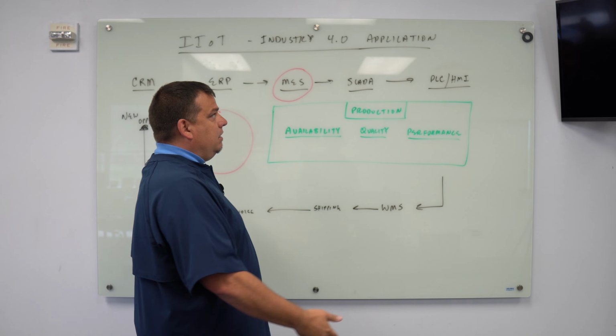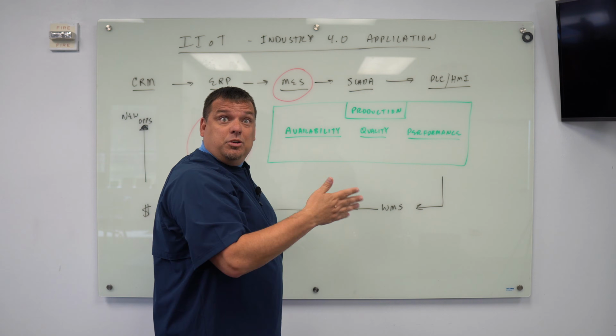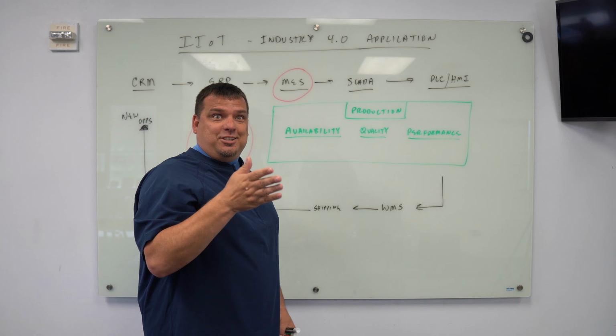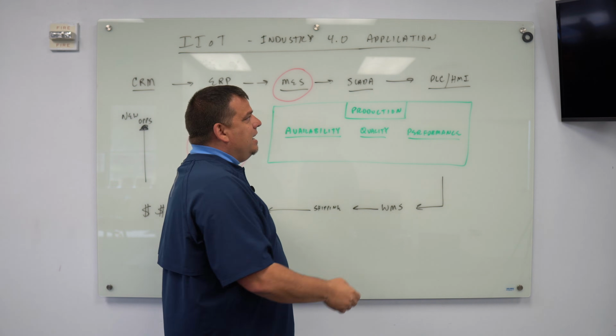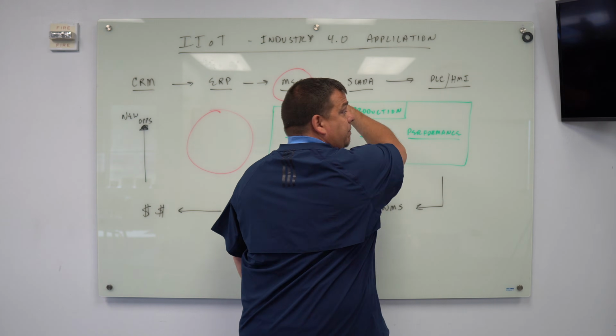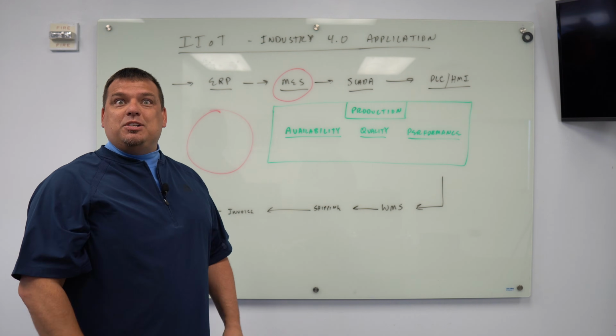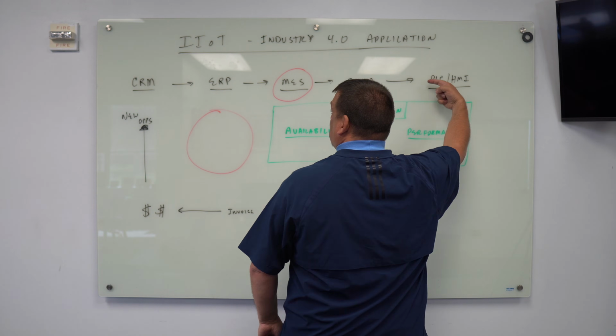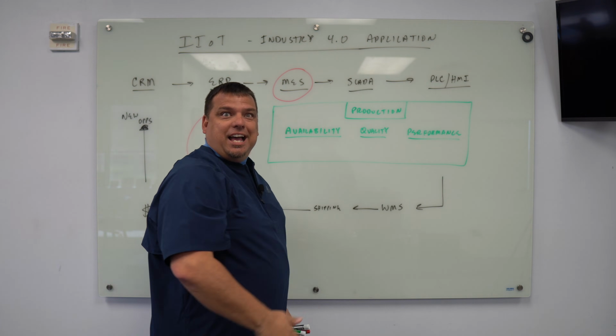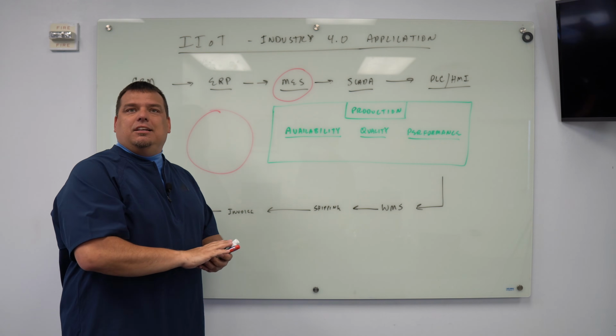How do we address that? Network address translation. We use NAT, which turns multicast traffic into explicit unicast traffic, number one. And number two, we use outbound-only, report-by-exception technologies, IIoT. There are no inbound open ports. Everything publishes out from the edge. Again, it's pure ignorance.